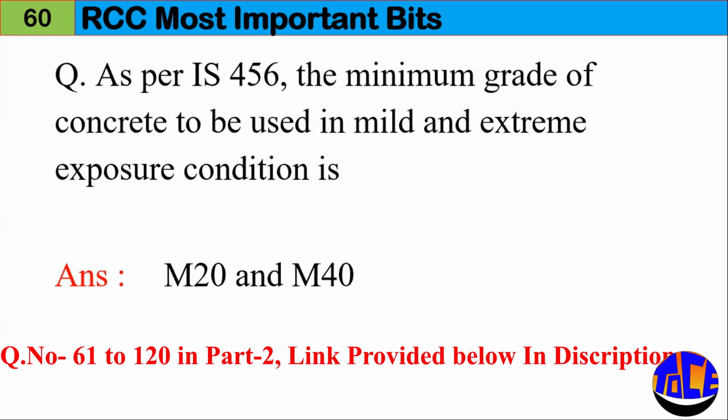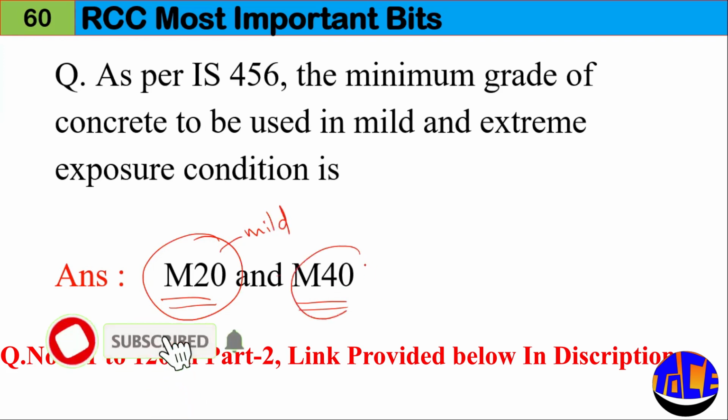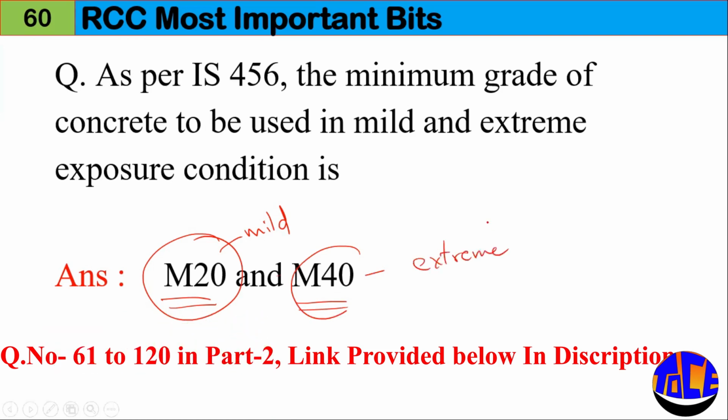Question number 60. As per IS 456, the minimum grade of concrete to be used in mild and extreme exposure conditions is M20 and M40. So M20 is for mild exposure condition, and M40 is for extreme exposure condition.